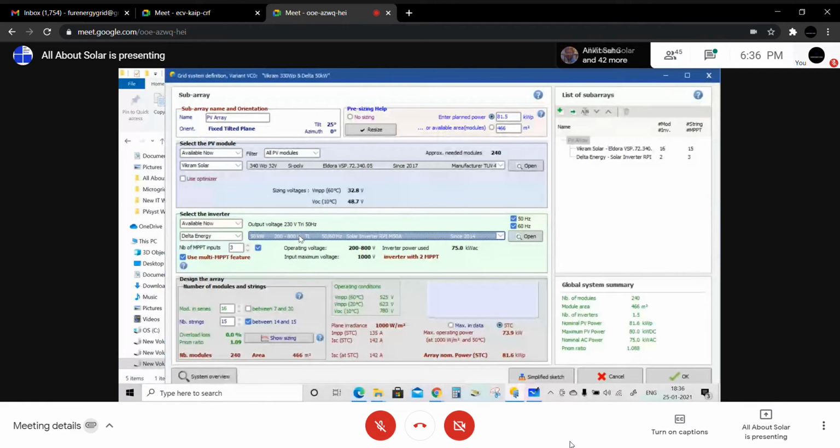When you are using a string inverter, there will be sections of the inverter known as MPPT. MPPT signifies maximum power point tracker, which divides the inverter into specific sections to maximize the plant power and to give you flexibility in string sizing. What does that mean? When you are working on a specific design and choosing the strings, you find that some strings have 18 modules and some strings have 19 modules.